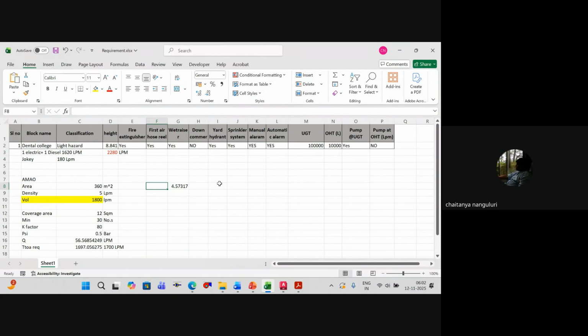Okay. So Chaitanya, yes, please. Anil, is there a limitation on the depth of the water? Yes, it should not be below 6.5 meters, if I'm not wrong. 99% I'm sure of that number. But anyway, tomorrow I'll refer you to that particular clause as well. The height of your tank should not be below 6.5 meters from your road level. Tank depth obviously reflects the water depth. It cannot be lesser than 6.5 meters, obviously I can't even have my water level lesser than that, right?